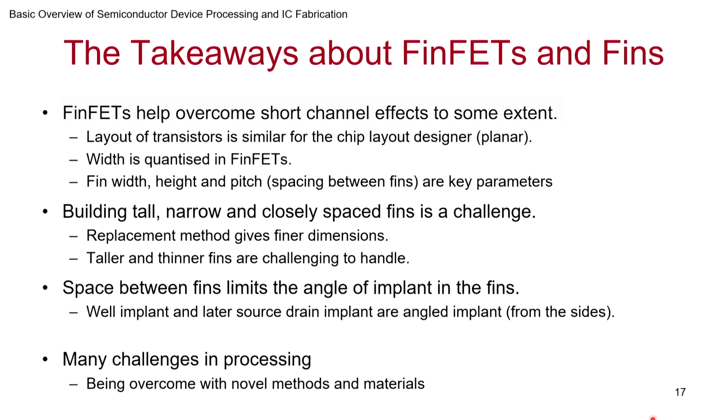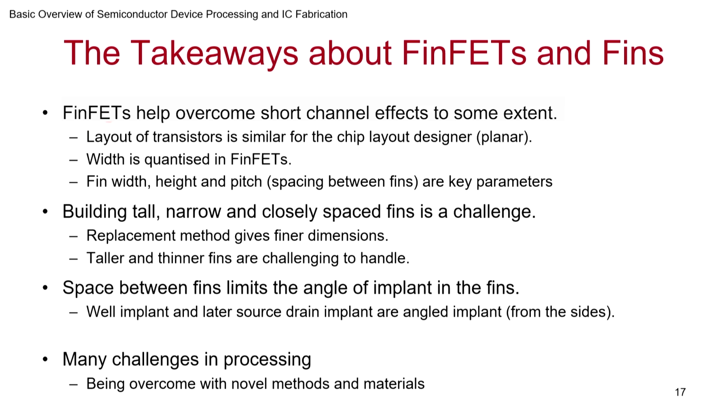So let's take a look at the takeaways about FinFETs and fins. What did we see in this? FinFETs help overcome short channel effect to some extent. I say to some extent because now the demand is even more, so you have to go for a gate all around. The layout of the transistor is similar. As far as the design engineer is concerned, the rules were given to him or her in the same way. The width, of course, is quantized in FinFETs.